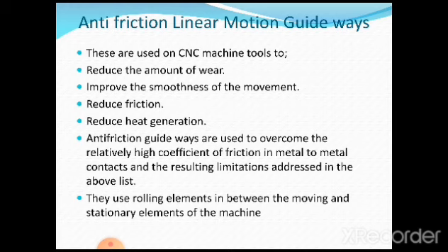prevented there. To improve the smoothness of the movement, the smoothness can be achieved very correctly compared to friction guideways. To reduce the heat generation, there is no heat generation because there is no friction, because there is no direct contact between the two parts. No stick slip. Unlike friction guideways, there is no question of the stick slip phenomenon. So this can be reduced to zero.